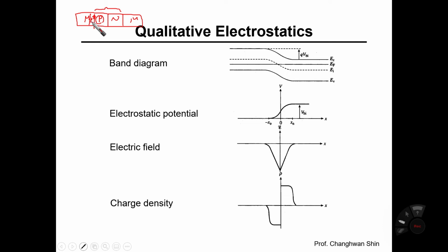Therefore, heavily doped P++ silicon material is necessary to build the ohmic contact between the metal pillar-type contact and the heavily doped semiconductor region in the P-type silicon substrate. And of course, we definitely need an N++ heavily doped region to build the ohmic contact between metal and N-type semiconductor. So in that sense, we need a very heavily doped semiconducting region.